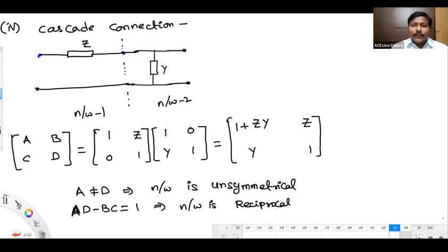Kalyan, that is what I said. You take that as a two-port network and calculate it. Take V1, I1 on one side and V2, I2, the voltage and currents, on the other side. Apply KVL and KCL and you will get the ABCD. Follow the procedure of ABCD.